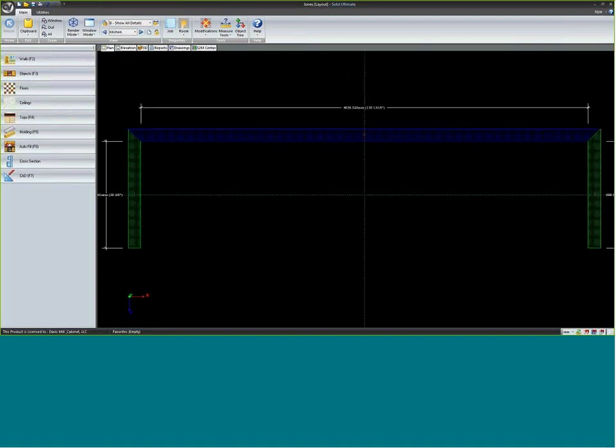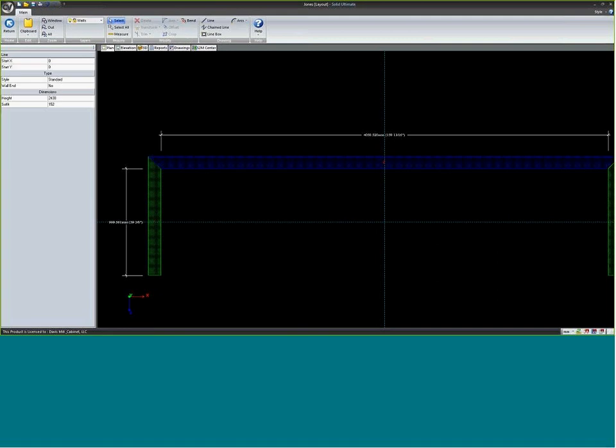If you need to do inches, one thing you can do, for instance when drawing walls: if I want to put in 8 feet, 96 inches as a wall measurement, but I'm drawing in millimeters, I can start drawing a wall and use 96 inches times 25.4. That's your conversion factor for those that don't know.